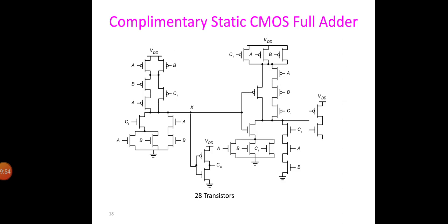For instance, in stage k of the adder, the signals Ak and Bk are available and stable long before Ci,k arrives after rippling through the previous stages. So in this way, the capacitances of the internal nodes in the transistor chain are precharged or discharged in advance. On arrival of Ci,k, only the capacitance of the node X has to be discharged. And putting the Ci,k transistors closest to VDD and ground would require not only the charging of the capacitance of node X but also the internal capacitances.